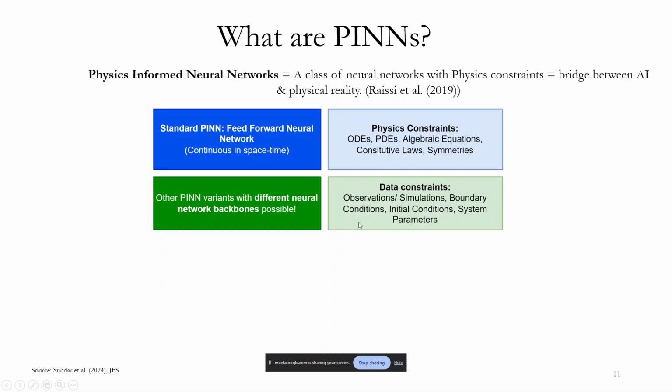So this is a very interesting class of inverse problem called hidden physics recovery. Another use case is unsteady flow with sparse moving bodies. Let's say you have a moving body in the domain, and you have some sparse flow measurements or simulations, or dye concentration like the earlier, and then you could train these models to reconstruct over the entire domain what the wake field would look like and what contributes to effective flight of these natural flyers or swimmers. Then also recover the load generating mechanisms, like how do these birds generate lift or thrust, and that is where you look at pressure as the hidden variable and recover the loads on the surface of the body.